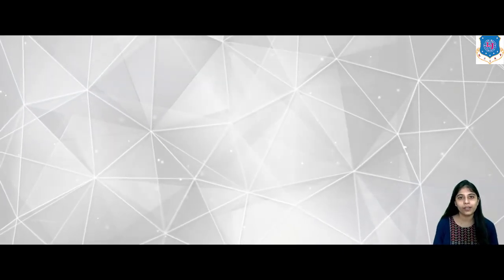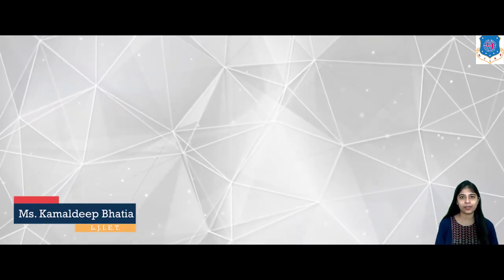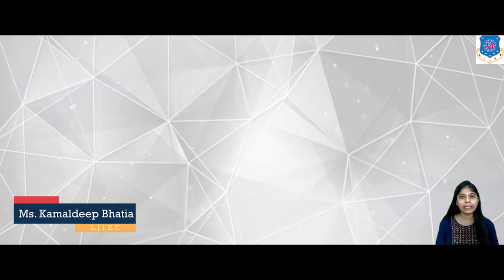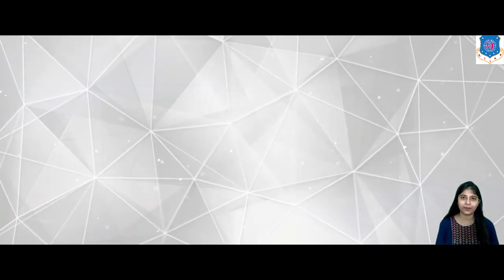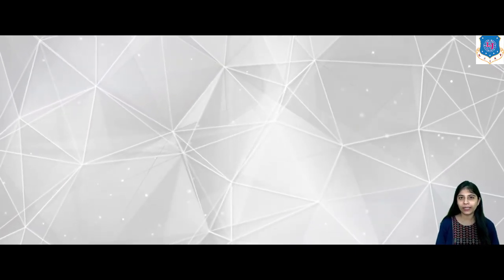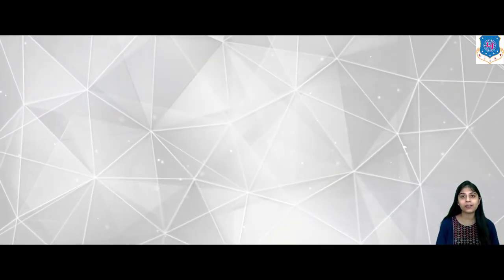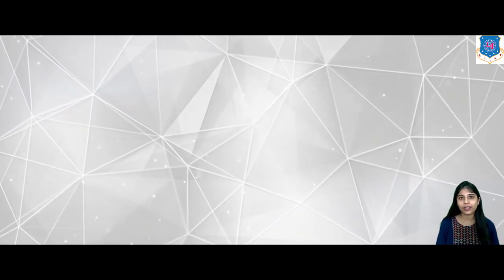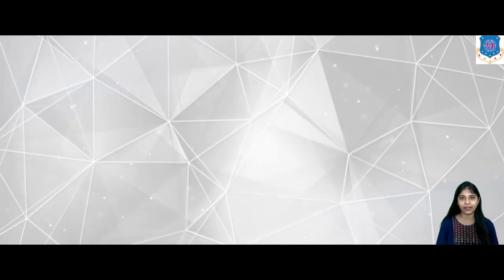Hello everyone. So in this session we are going to study modulus of elasticity. There are three types of elasticity corresponding to three types of strain. The first one is Young's modulus corresponding to linear strain. The second one is bulk modulus corresponding to volume strain. And the third one is modulus of rigidity or shear modulus that corresponds to shear strain.